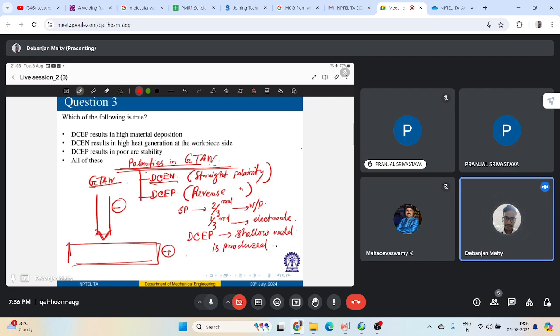As a result, the starting of the arc will be easier, and the arc will be more stable if you are mixing those cerium or thorium with tungsten electrode. Electron emissivity refers to the ability of your electrode tip to emit electrons, as I was saying.